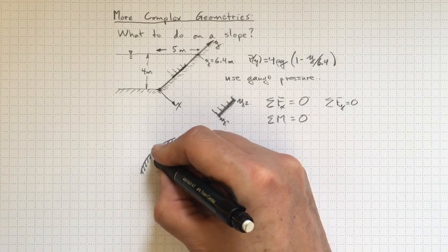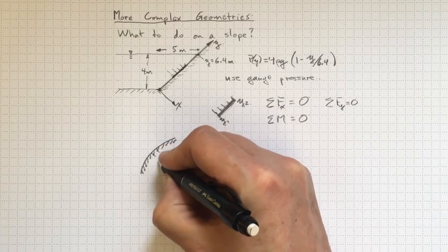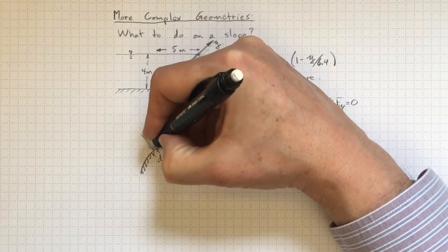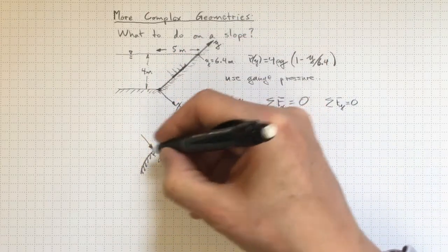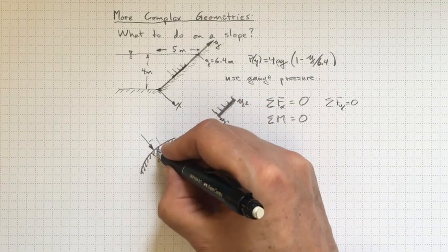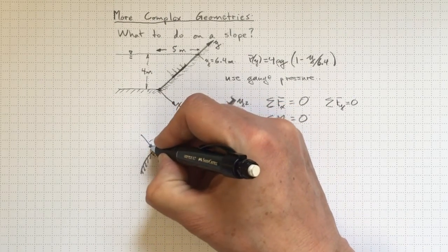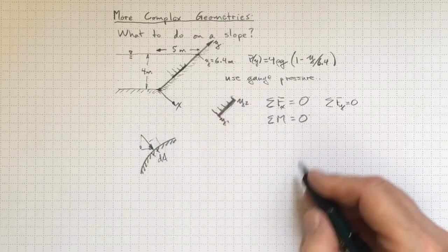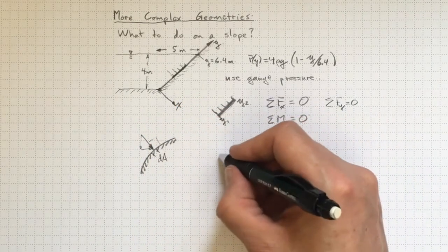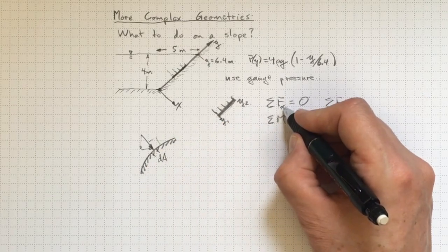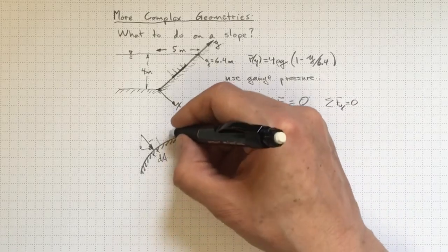But if we consider a small incremental area on here, and we consider our pressure force acting perpendicular to the local surface dimension on that area, then we'll have this force, which we can break into components in the y direction and the x direction, and we can use our integration over the entire surface to sum up all of the forces acting in the x direction.